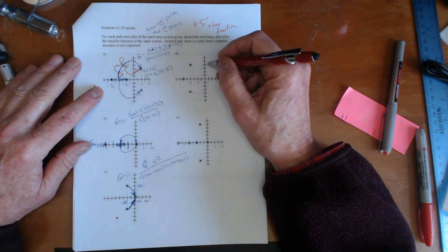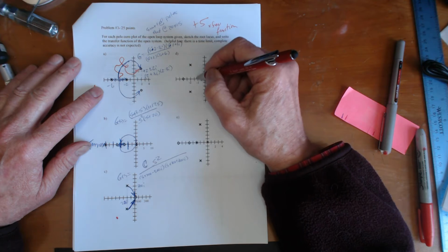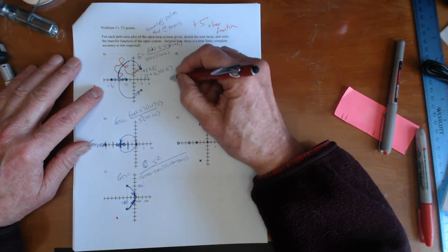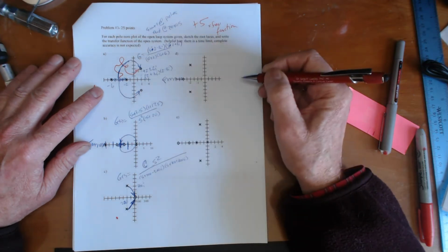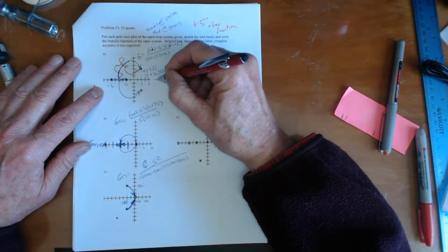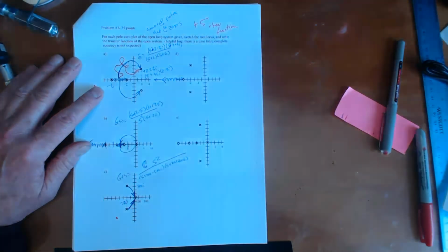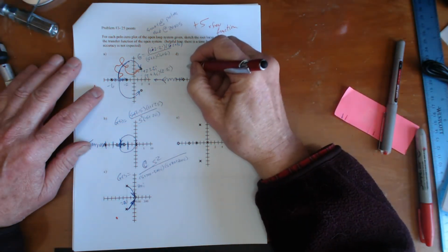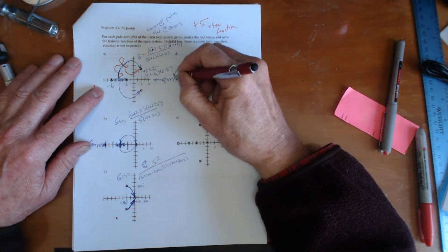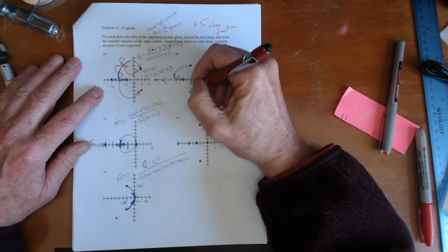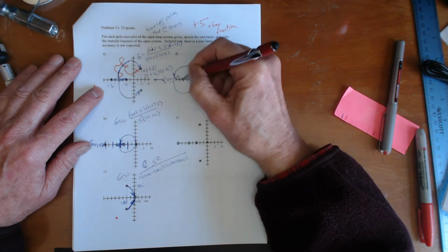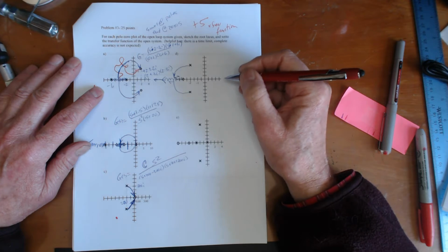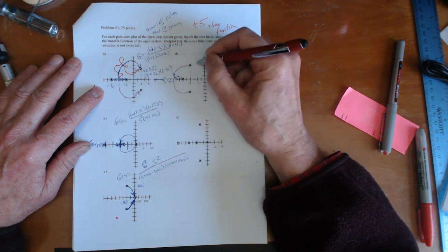Okay, again, so here we are, real axis segments, 0, 0, 0, 1, 0, 1. How many asymptotes? Just one. Here's the asymptote going off in this direction. And then what we would do is we would know that these things have to come in and hit the real axis in some way. One of them goes towards the finite zero, and one of them goes towards the infinite zero. Again, this is going to be minus 2.